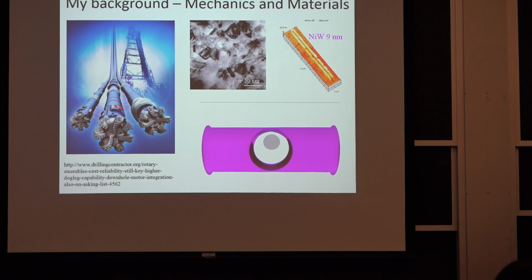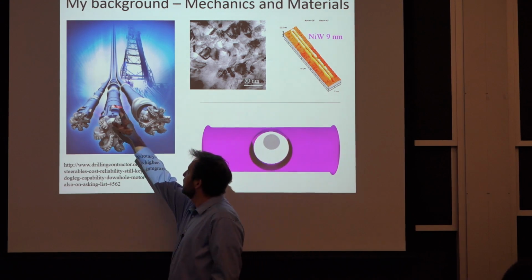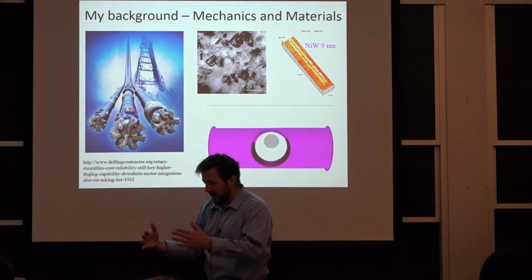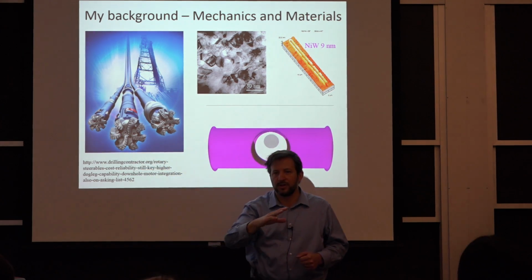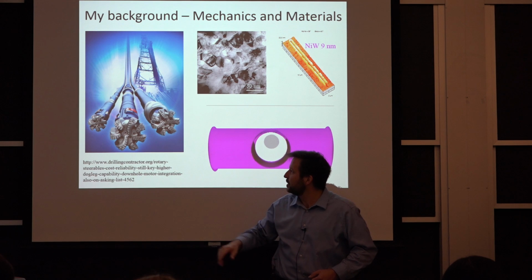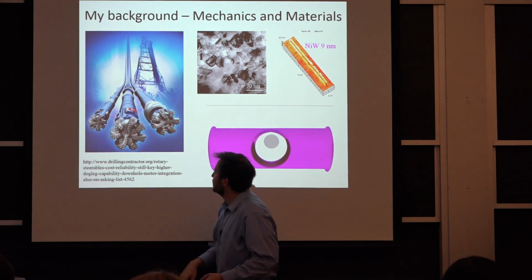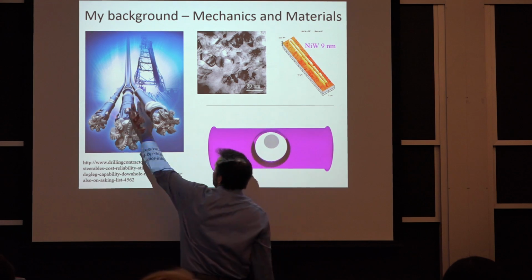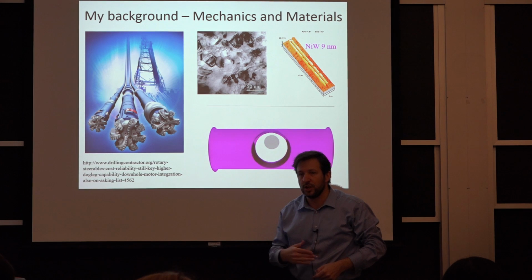And what directional drilling means to them and other people in the industry is you have a steering function, so you have pads that will allow you, as you drill, to continue to orient. So if you have the little red pads here, you have 3 of them around it, and you have a stabilizer in the back, and you just actuate these as you turn to change your orientation.